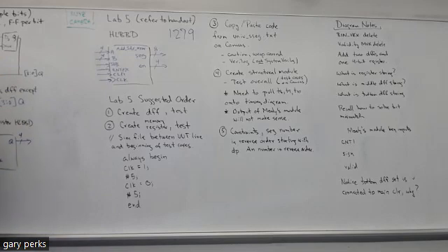So you would want a case where you're not resetting, you're not setting, you're not entering, and you want to make sure that the output stays the same, that it retains whatever it was previously. If it was a 0 before, it should be a 0 after. If it was a 1 before, it should be a 1 after. What else do you want to test?